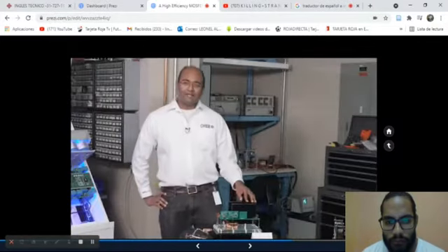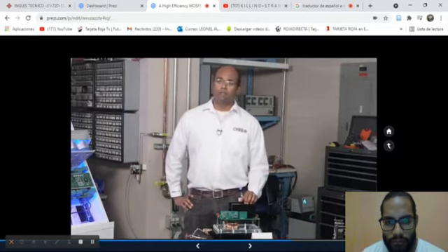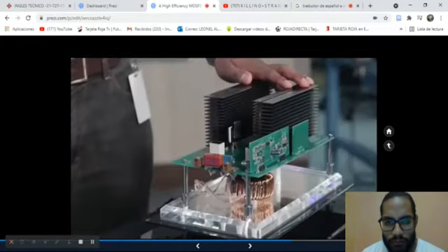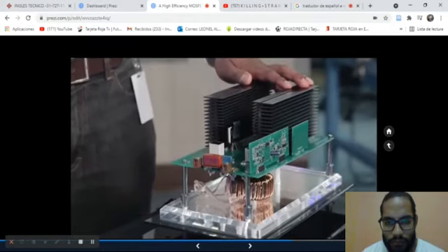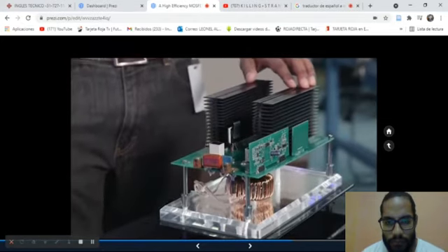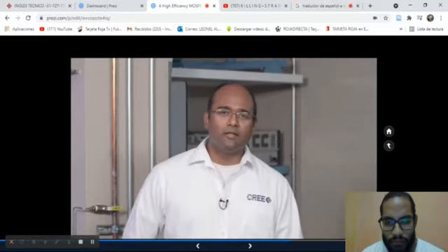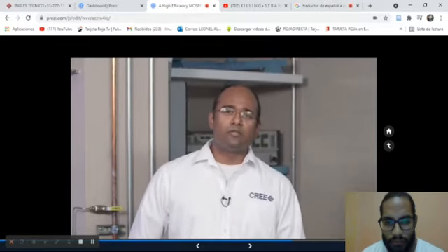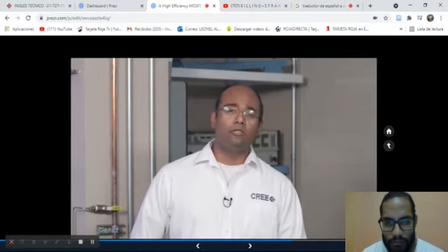First up is a 10 kilowatt boost converter that we designed for the PV market. So these boost converters are used in PV string inverters. And what we wanted to do was build a reference design with silicon first using IGBTs. These are high voltage inputs. So using 1200 volt silicon IGBTs, and then compare that to a solution if we had used silicon carbide devices instead.